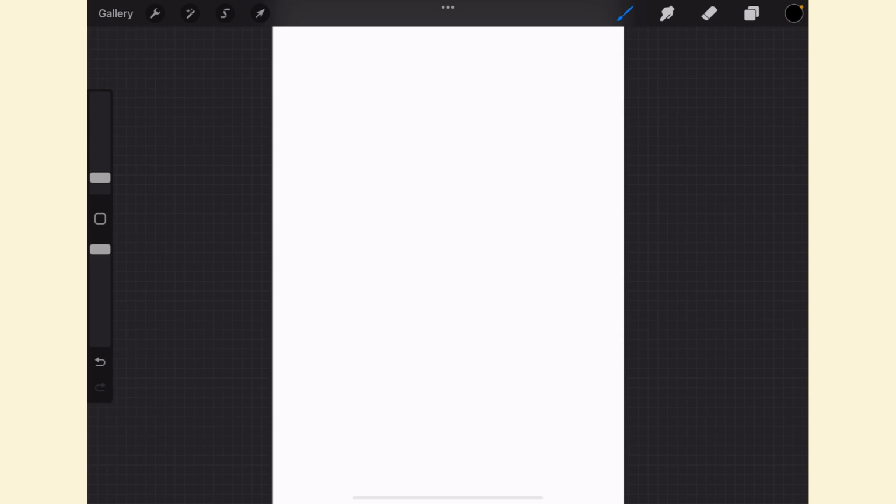So, we can calculate the pressure altitudes directly by calculating the height where such particular conditions of pressure exist. Since the temperature is given as 255.7 Kelvin, which is in between the sea level value and the value for 11 km, that is 216.66 Kelvin.